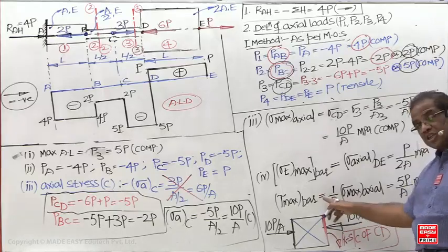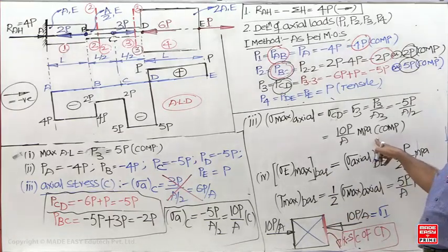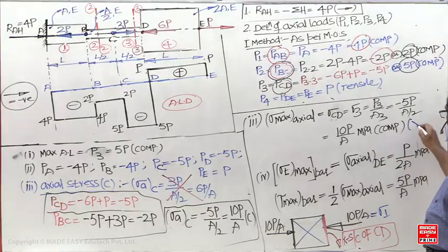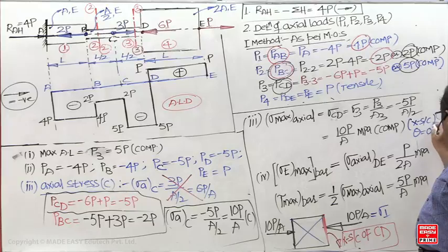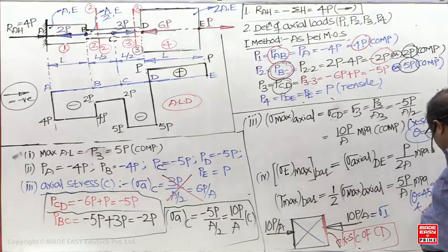So on this cross section, shear stress is 0. But this much of stress that you get on the cross section is at an angle of 0 degrees. But the maximum shear stress you get at theta equal to 45 and 135.